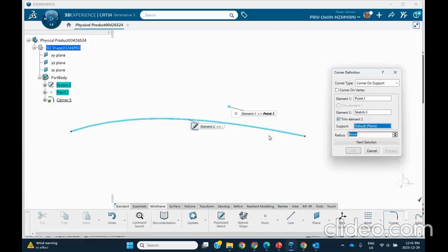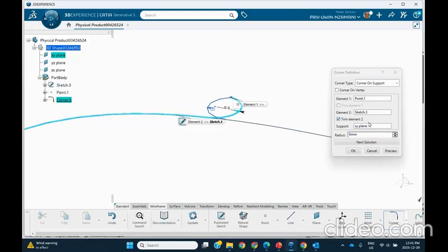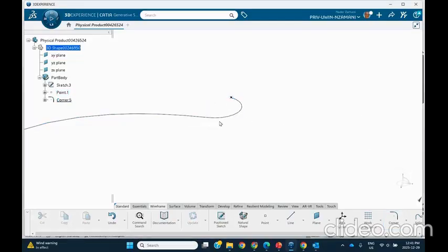Now, 6 millimeter may not give you a circle here. And oh, by the way, when you select this point, this default plane is not going to do you any good. So I'm going to select the XY plane. You see that? When you use a point, that default plane may not do you any good, and it doesn't. There are 2 solutions here. You can see this one or that one. For example, if I select this, it's going to be that curve. Let me delete this.